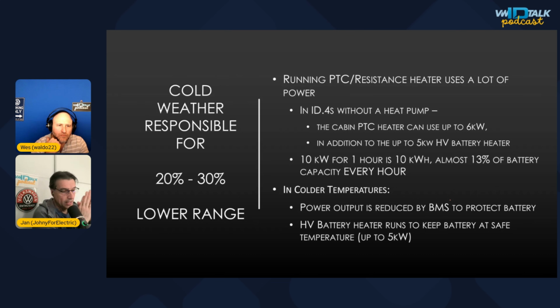If you live in a space where you have level 2, or if you have a charger where your car sleeps with you, or where your car is while you're working, then you can preheat the battery before you go, because it helps to take the energy from the grid versus from your battery to preheat the battery. That's one. And two, obviously, if you're using direct heating, like heated steering wheel or heated seats,